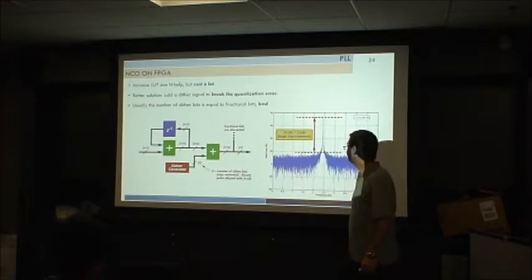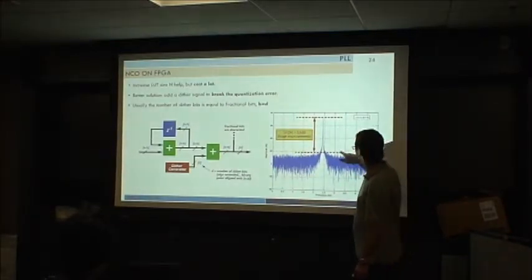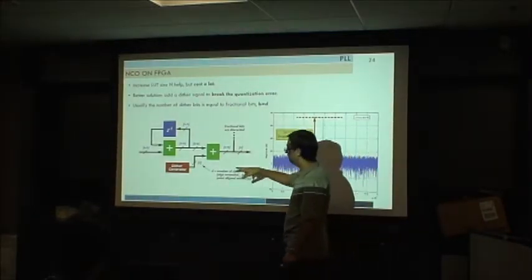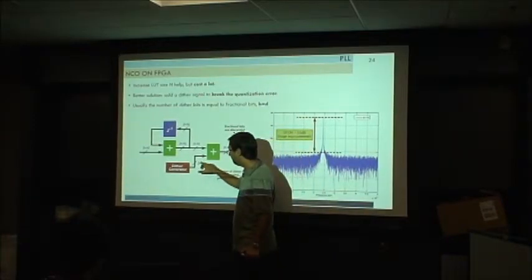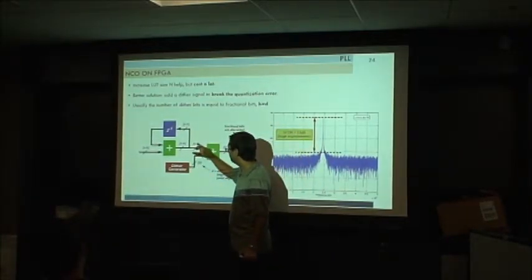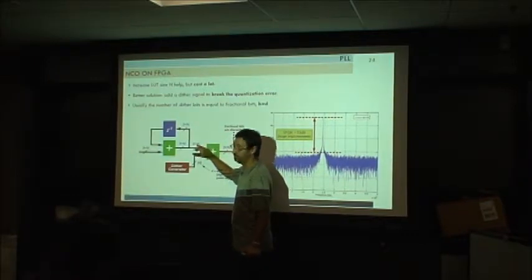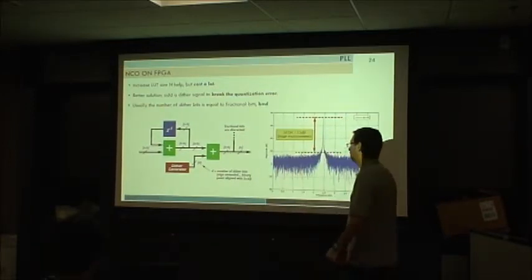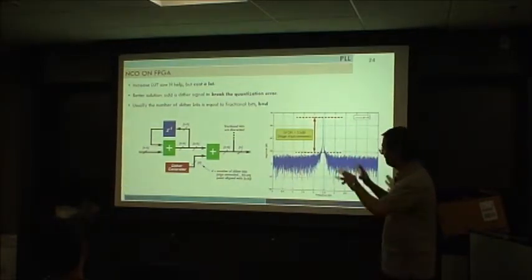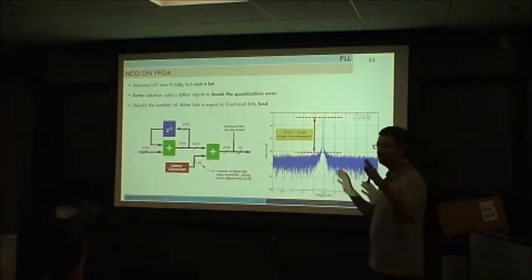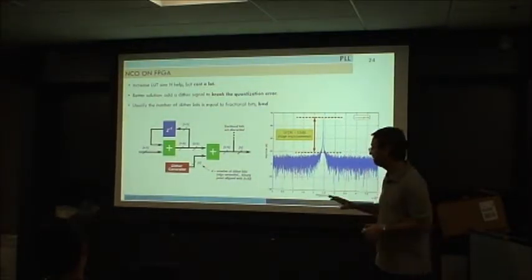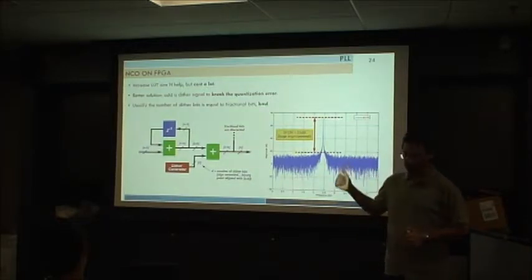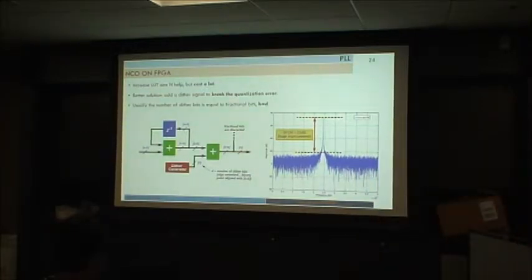So when you do that, this graph shows that the number of bits on the jitter generator is exactly the same number. Let's say you have 6 bits here, this generator creates 6 bits. This is something that always works. And with the same numbers as before, with no added L or n or whatever, just adding this, you get a much better result. You improve almost 30 dB, because the previous one was 30 and this is 50, so 23 dB.